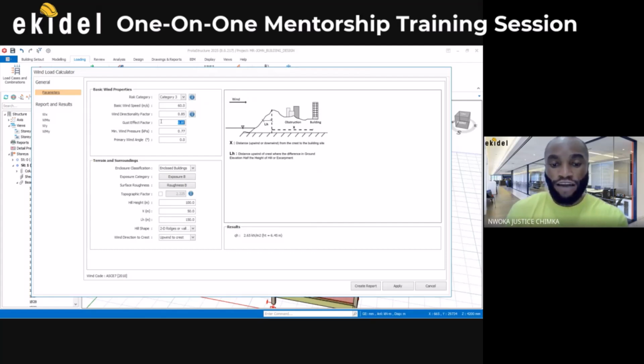For example, if I use 0.5 now, by the time we choose our exposure class and all that, you see that the value here will increase. Right now, let me just choose 0.85. I believe in the code too, you'll be able to see the range of the gust factor based on locations or cities. Understand? You'll be able to choose that.